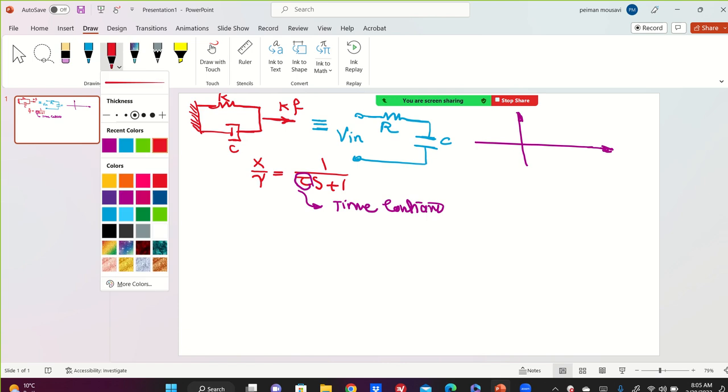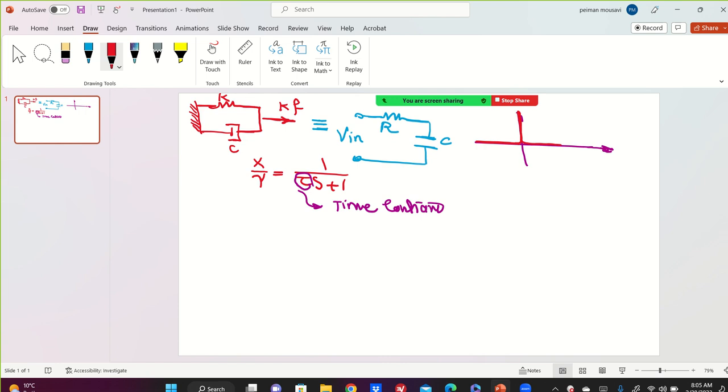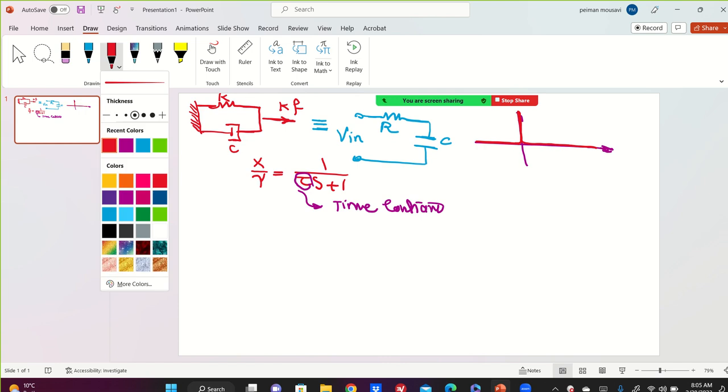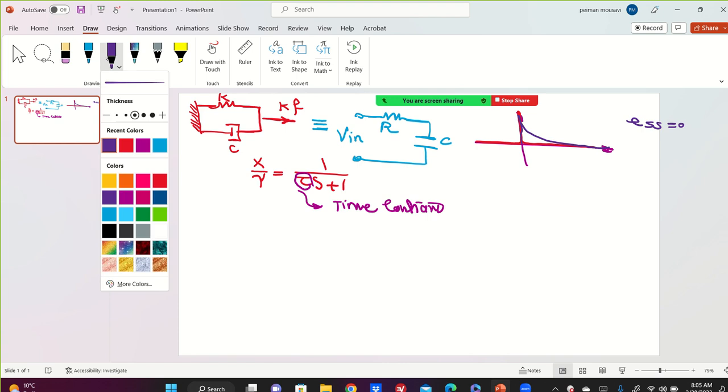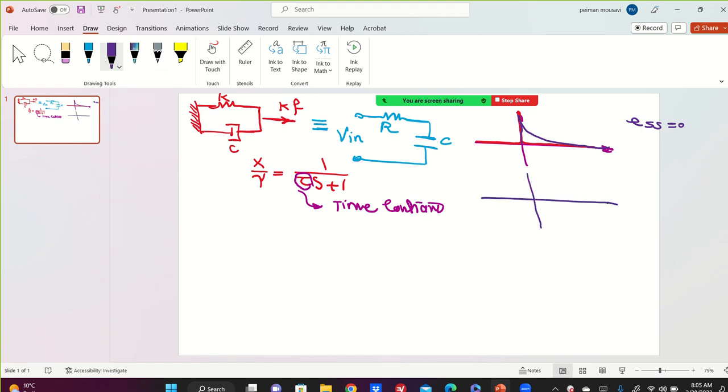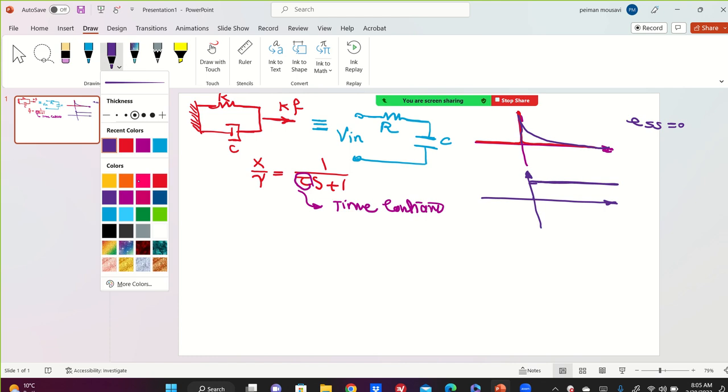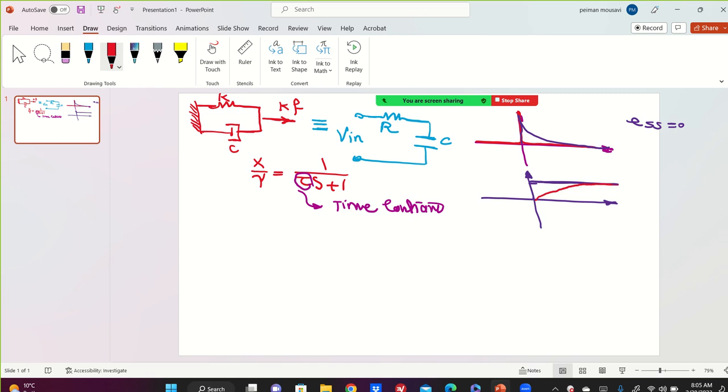input is in the form of an impulse, the output is going to be this, so the output follows the input, so ESS for the impulse input is 0. Then I showed that if the input to the system is a unit step, the output of the system is going to be this without any oscillation. So again, ESS, the steady state error signal, is 0.